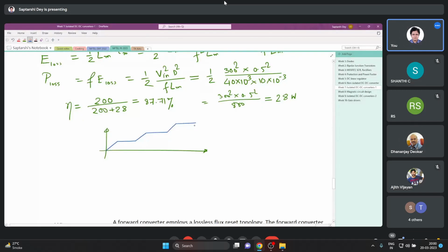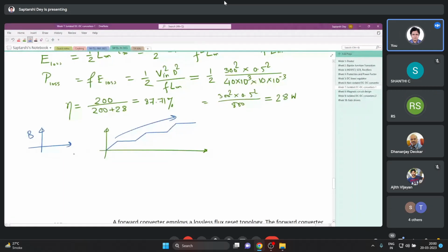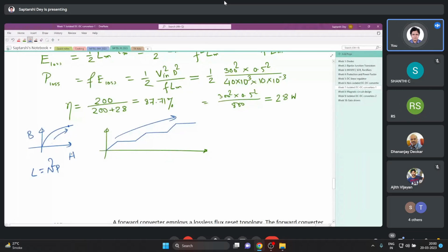Why short circuit? I think we discussed if L is there. No, see, we have to somehow move away that energy. L cannot dissipate energy. The more we go into this zone, the lower the permeance. Inductance is n squared times permeance, so lesser the inductance. V equals L di dt. So for the same voltage, if L drops due to saturation, the current will see a sudden large increase and short circuit the supply voltage.